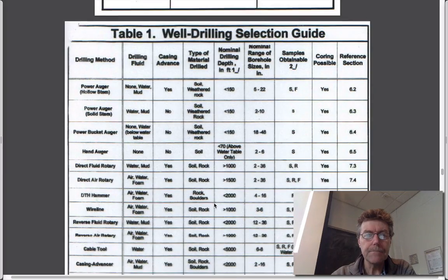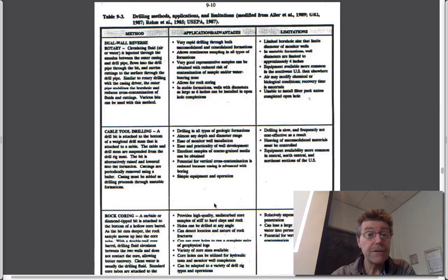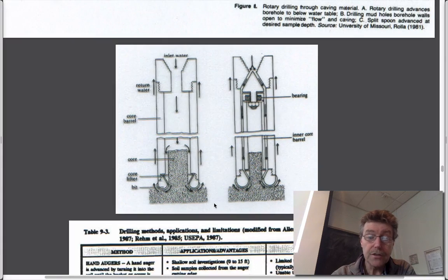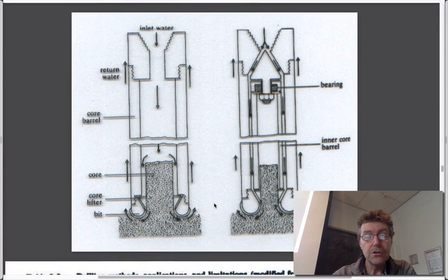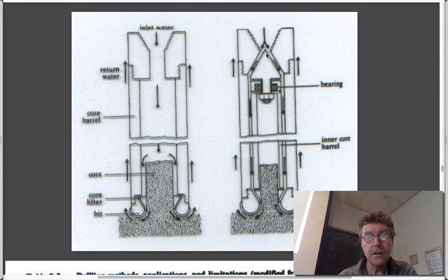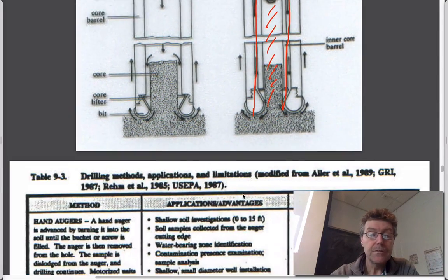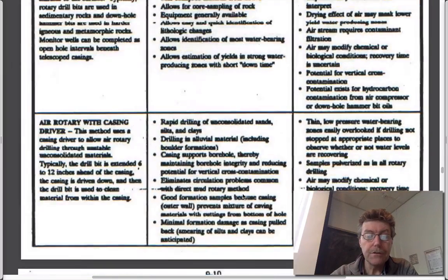Yeah, so this is it. This is where we finished up last time. I didn't go through these word components, but we talked about diamond drilling. So you remember the last thing we talked about was using wire lines to be able to go down inside the hole, pull out this whole core barrel with the core that exists inside that, and leave the drill string down the hole, so you have casing that holds your hole open and you don't have to worry about anything else collapsing. So we talked about a variety of different methods of drilling.